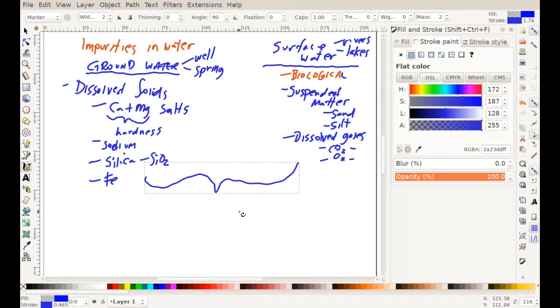Now, in the plant where I worked at the generating station, we had both sources. One source of water was river water, and the other source of water was a ground, like a deep well source. And so the deep well water had a fair amount of iron in it. The deep well water had some silica in it, and the deep well water was fairly hard.